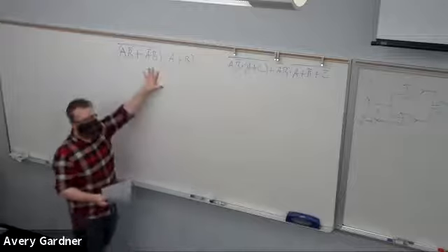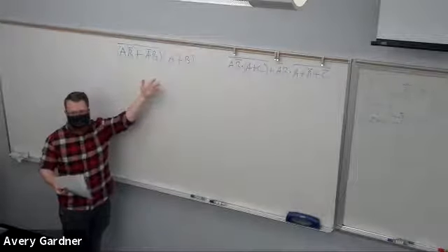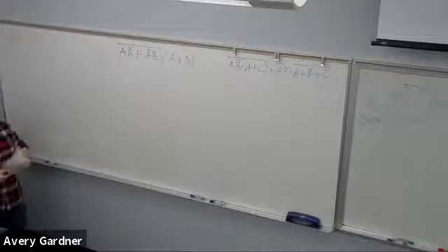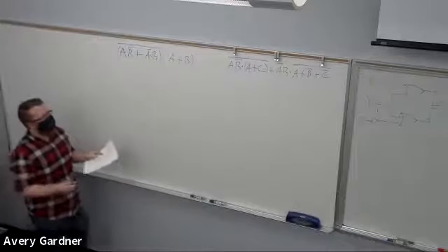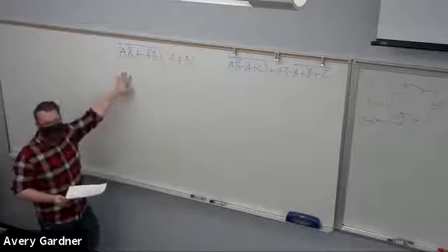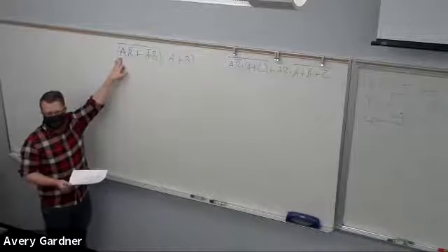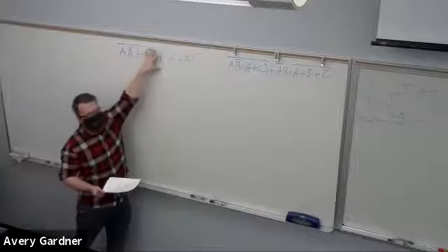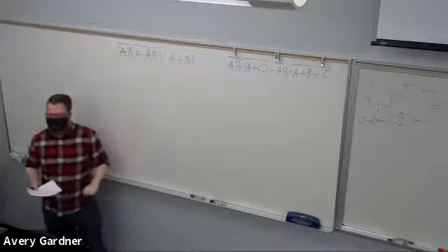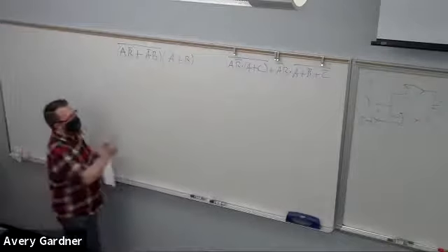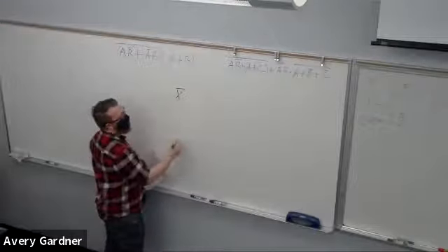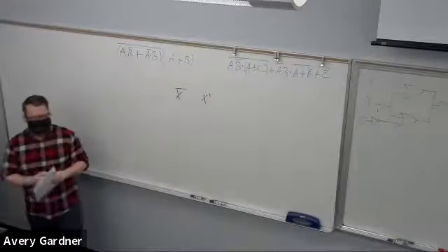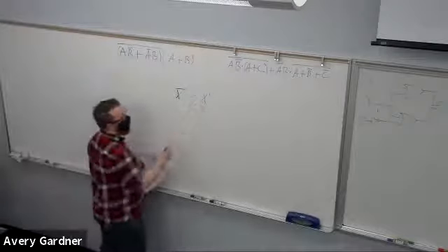We also talked about Boolean algebra, and I'm going to go through some examples so we can see that, because the Boolean algebra tends to get people stuck and confused. And both of these have something in common. What theorem are we going to have to use to simplify these? De Morgan's theorem, right? Because you have many terms underneath a not bar. Remembering that I can write not x, is that or that? Right, those are equal.